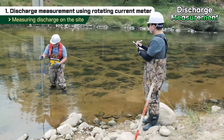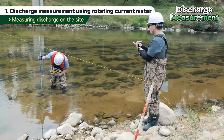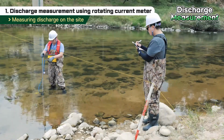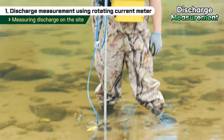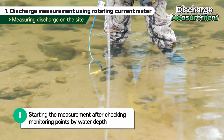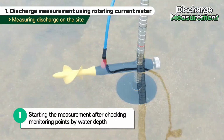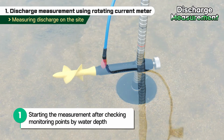Having completed the default setting of the user terminal and checked the water level, the measurement of the current speed starts. Since it should be measured by changing the monitoring points according to the water depth of the stream, water depths at the monitoring points are checked with the sounding rod, and then the measurement of the current speed starts by adjusting the installed location of the main body of the current meter.